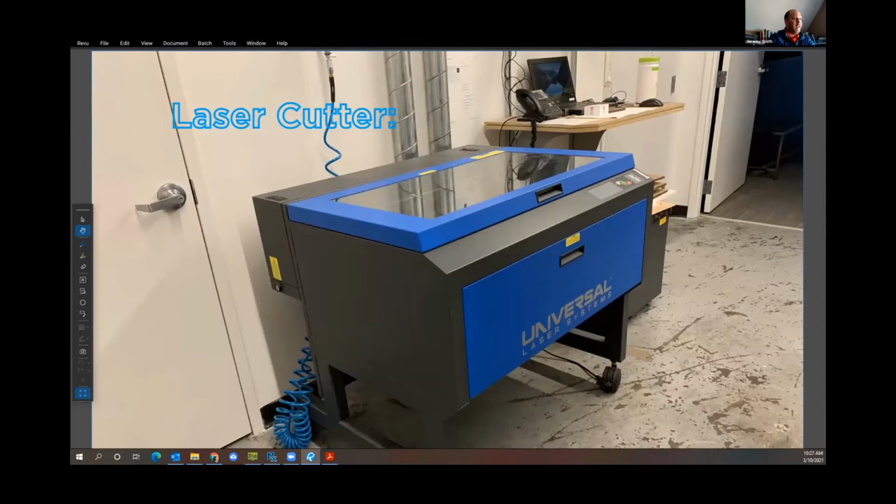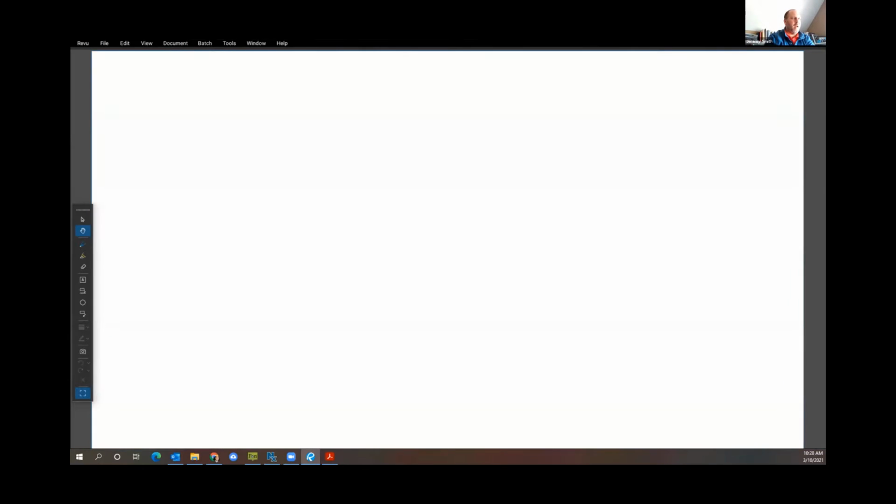This is a laser cutter. It's very similar to the one that's at ThinkBox. Usually laser cutters are attached to a laptop or desktop in some way, where you'll import your line work into a program, and then that program will take probably the three line types that you have. That's either a cut, a score, or an engrave, and determine the depth of the material, and you can cut things that might take you a lot longer to do by hand.